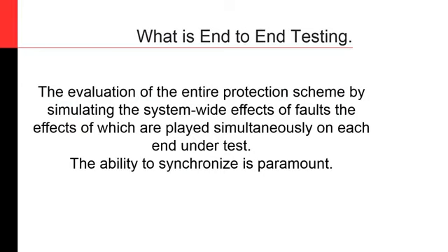So this is a definition that I came up with about what is end-to-end testing. You will find as many definitions as people approach in the field, but everybody agrees in the fact that end-to-end testing is a way to evaluate the entire protection scheme by simulating the effects of faults on both ends of the line, which have to be played simultaneously.